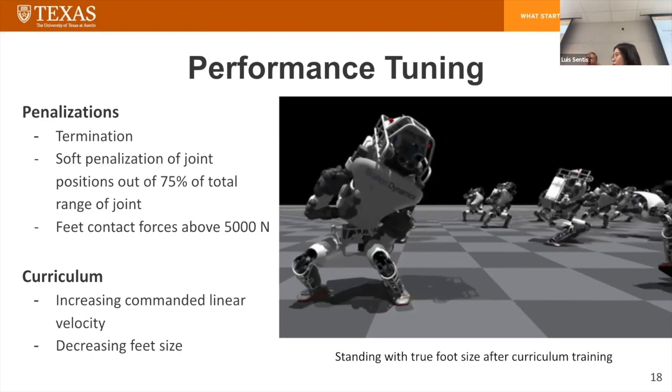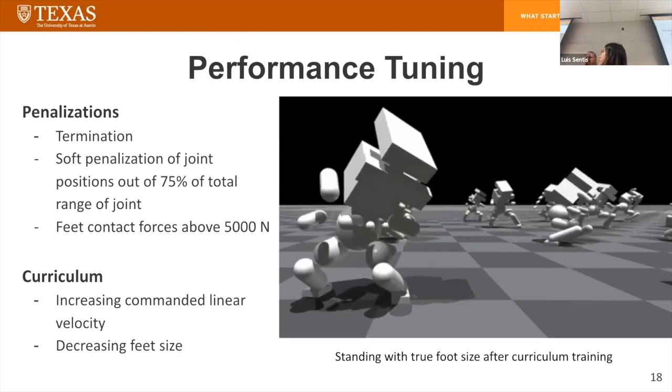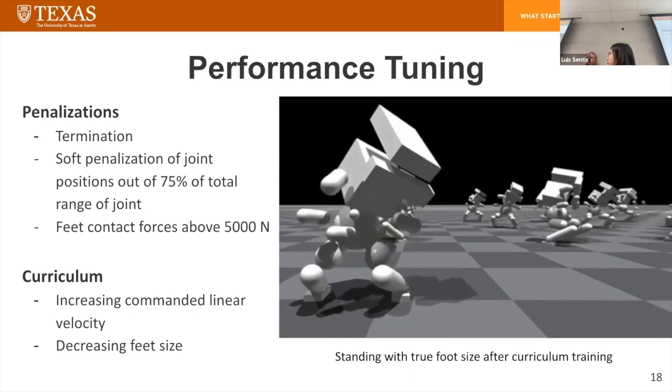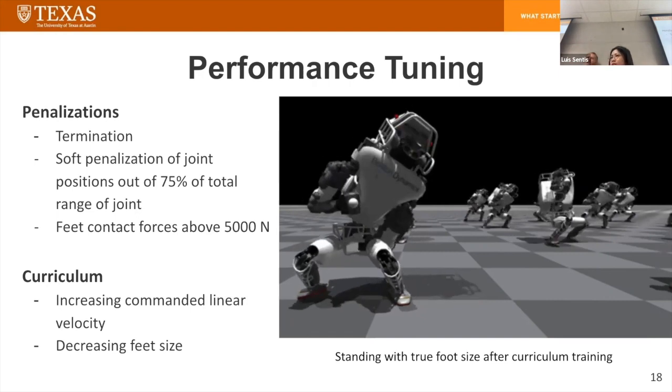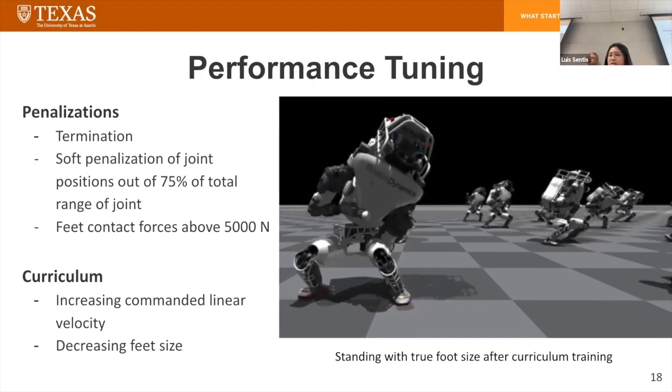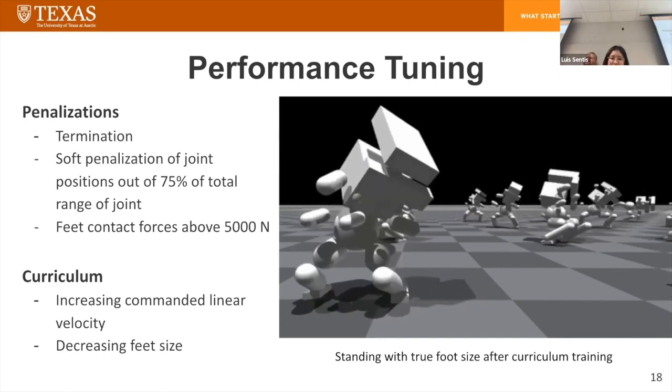We implemented these two curriculums. Like a gym comes with the linear velocity curriculum, where if your robot is able to walk at a certain velocity range where you get 80% of your tracking rewards, it increases the range so that it makes the robot walk faster. Atlas never really achieved 80%, so we never really saw any effects of that.